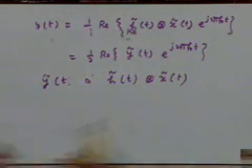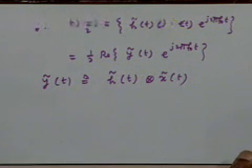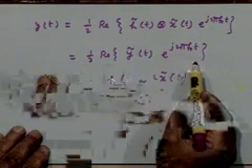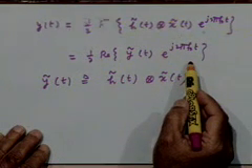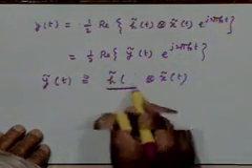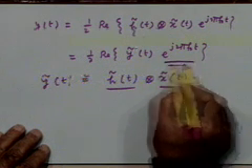Because it is x_r(t) cosine 2 pi f naught t, x_i(t) sine 2 pi f naught t, etc. Or even in the complex representation, I keep on carrying that e to the power j2 pi f naught t, e to the power j2 pi f naught lambda, t minus lambda. Those terms are not necessary to carry with us in all our manipulations. Directly deal with the low pass representations, carry out your mathematics, and the final result will be this, right? This is the point, because these carry the information. This is just a carrier term to be added.